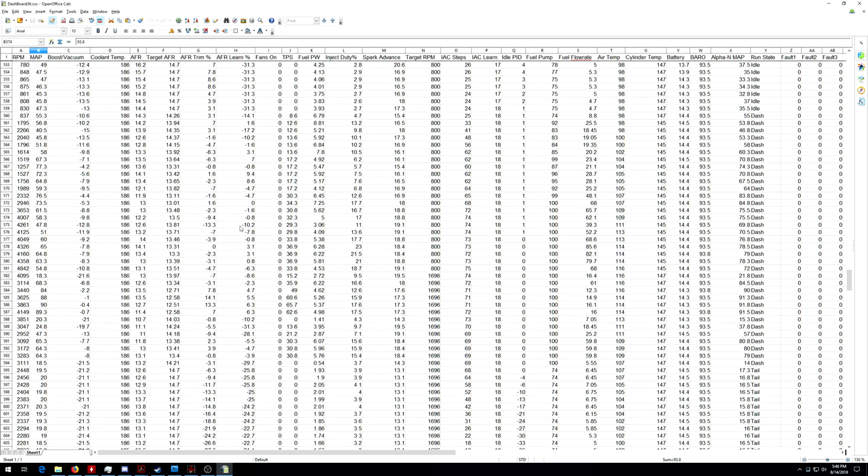This is when I left the parking lot, essentially, or back onto the main roads, getting up to the speed limits at a quicker rate than usual, I should suppose. You can see 30% throttle, 60% throttle. You can see your manifold pressures are in your mid-range, so between 45 and 95. Again, these are part throttle conditions, and ideally you want your system to run well at idle and cruise, in part throttle acceleration, and of course at wide open throttle. So this is where all this data starts to become useful. Gather it all in so you can make use of it later.